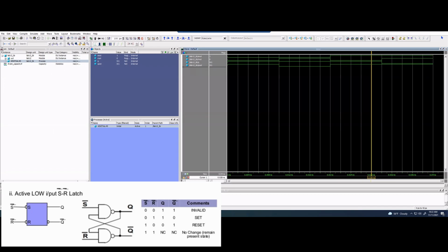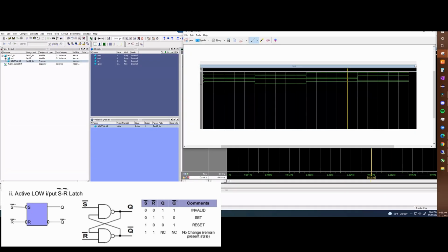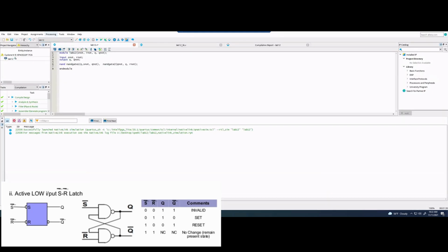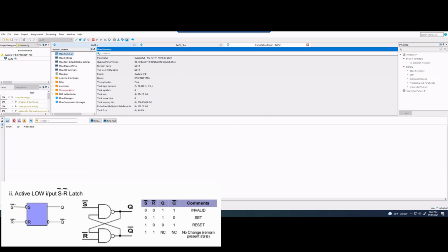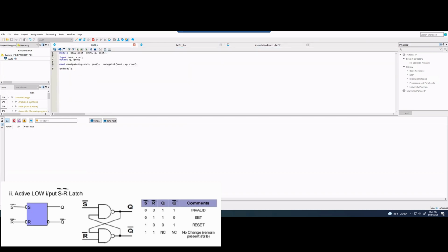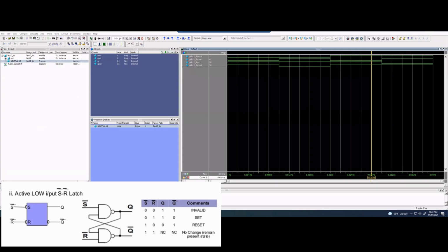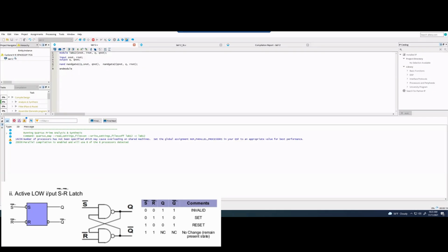So this is what it looked like previously. I'm just going to take a screenshot of it to make sure that we can compare it. We're going to need to recompile this, so we'll click Start Compilation. We'll click Yes because we want to save our changes, overriding the bad stuff, and now it's going to redo this. We're only going to compile this, and after this compiles, we will remake our simulation. Before we do that, we have to close our current simulation, which is why I took a screenshot. So yes, we want to quit this, and then we're going to wait for this to compile.